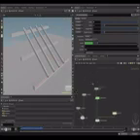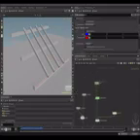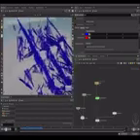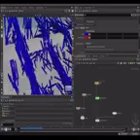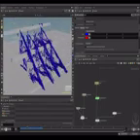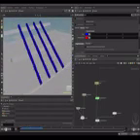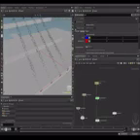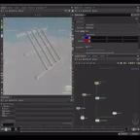Let me take a look at the geometry representation of it. As you can see, it's generating a convex hull geometry for each set of connected pieces. Maybe we can speed up this by setting the representation to box. Let me see if this goes faster and looks like a realistic simulation.